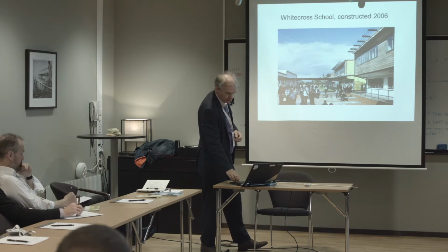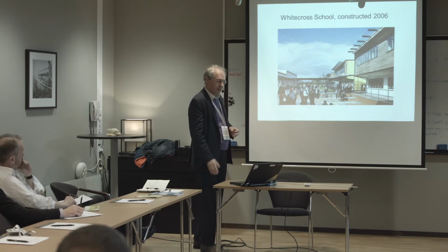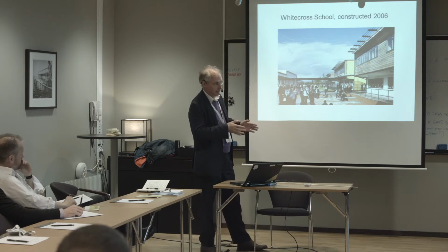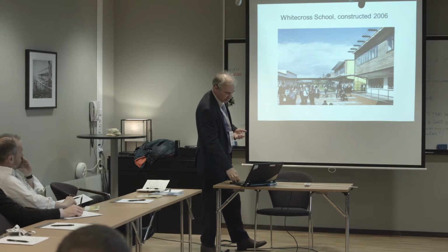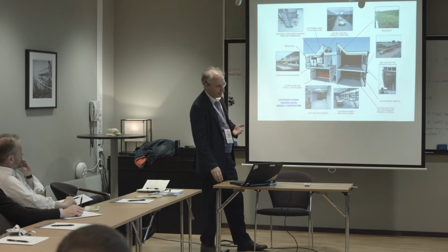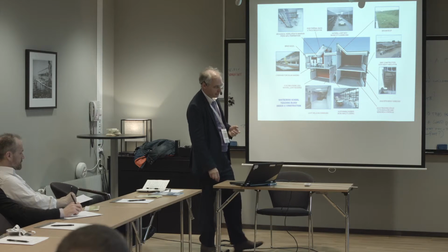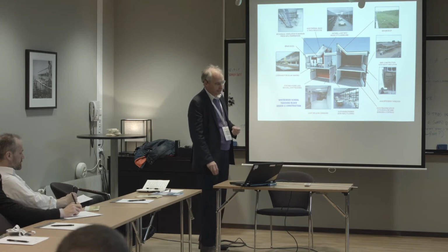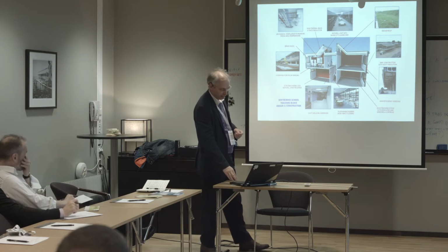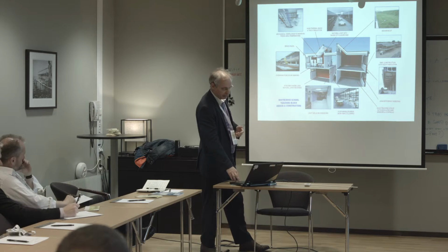This is White Cross School. It's got timber insulated panel walls, and it's got concrete roofs, and it's basically a passive thermal structure. It's also got very good daylighting on the top floor, and it's got a mechanical heat recovery system, a very, very simple one, with a central heat recovery unit, but no controls at the classroom level, because that adds sophistication which goes wrong in classrooms.